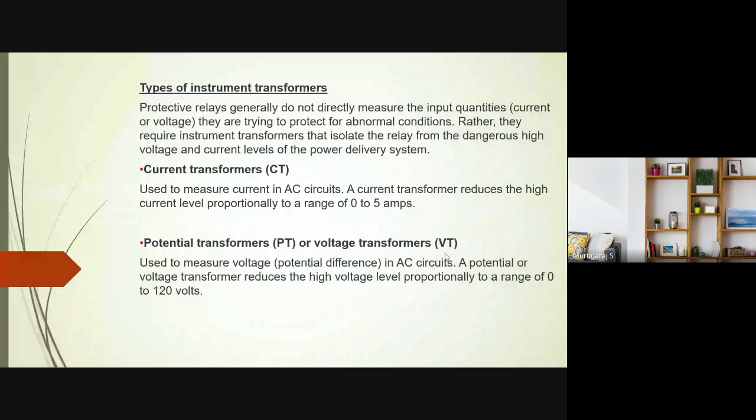This voltage will be given to the relay, and the relay will be programmed based on it. For example, if any kind of overload or short circuit happens, the voltage levels on the primary side change, and by sensing the resulting secondary voltage, the numerical relay will operate.